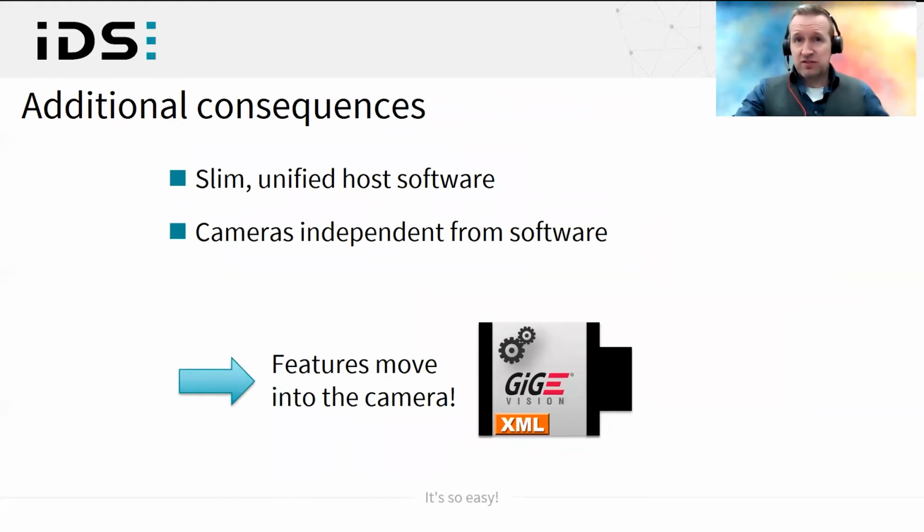However, the camera standardization also demanded important changes for the manufacturers. If cameras have to operate independently of a specific manufacturer software, they must themselves ensure that they generate usable output data. This means that functionalities for processing the raw sensor data must migrate into the camera. This includes functions such as debayering, gray level transformation, defect pixel removal, or white balance corrections.